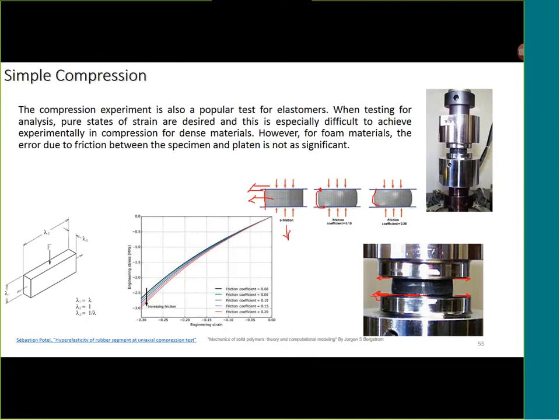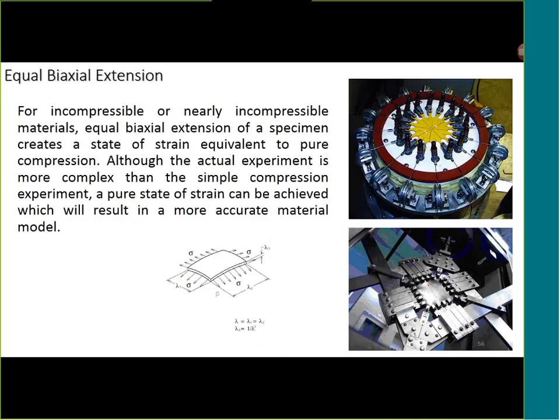There will be some minimum amount of friction. This friction is going to make some difference between the physical test data and the numerical simulation data, or the results coming from Ansys. You just need to keep in mind that it is highly recommended to provide as much lubrication as possible to induce a pure compressive stress state in your material.